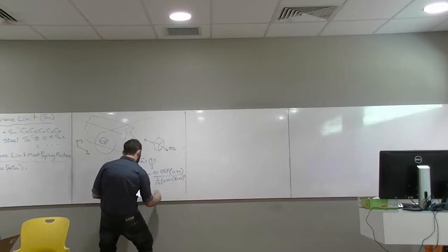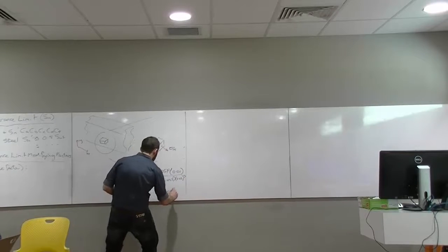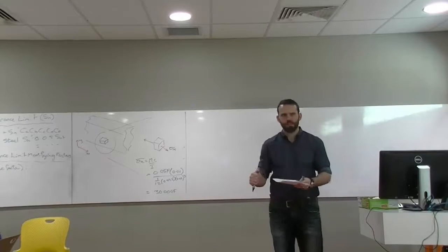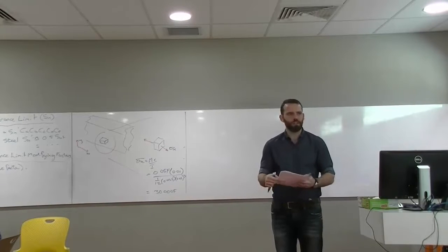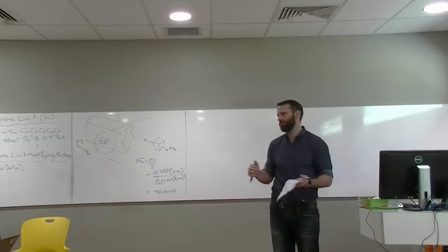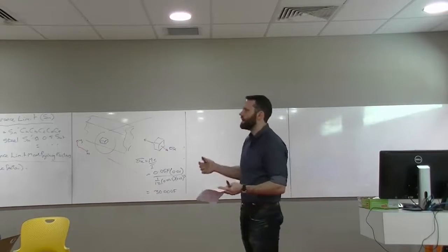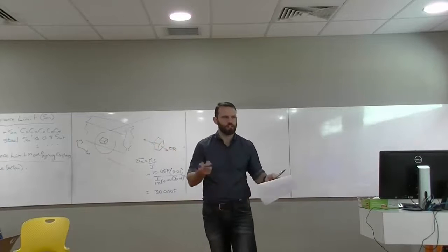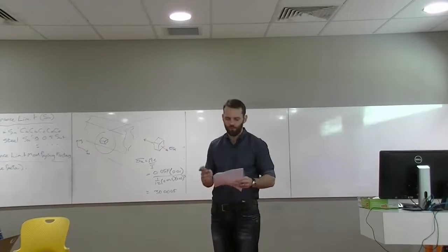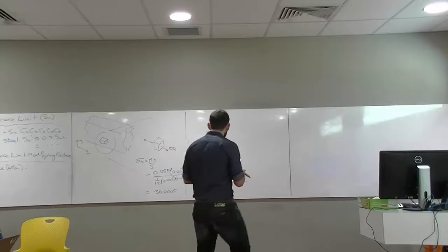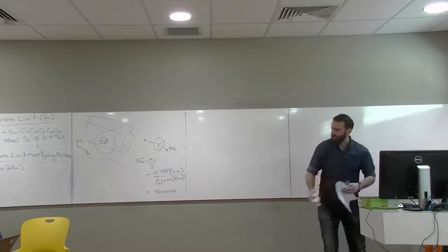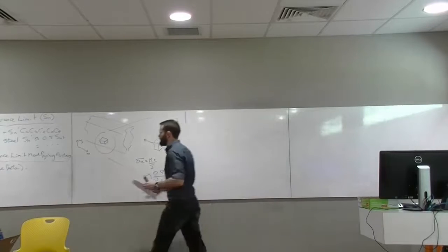I get 30,000 F. Do we have any stress concentrations to apply to that? No. So we can just ignore that part. Or Kt equals 1, Kt minus 1 equals 0, Kf equals 1, and you can put it to the front, but there's absolutely no point wasting your time. Alright, and then we do our layout thing. Looks exactly like that.